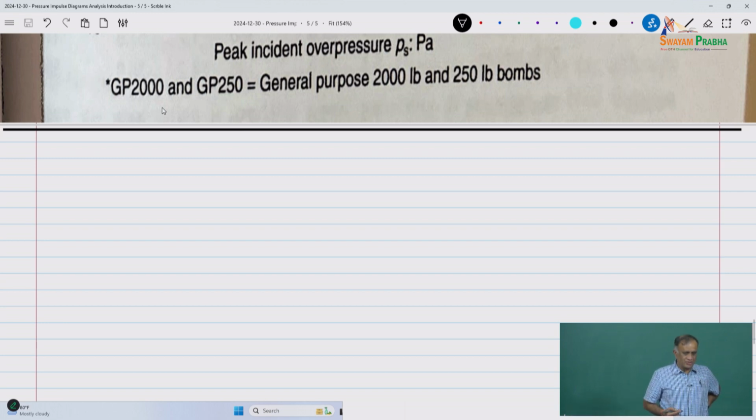So for example, the SDOF and whole Excel program of an SDOF response. You give a structure, maybe you can develop it for steel, concrete, masonry, precast, pre-stressed, anything that you want. So your inputs are going to be the structure properties, what are the sizes, usually if it's a wall, 1 meter width or 1 unit width is considered, and then develop all the section properties as we will discuss in the next couple of classes, and then develop the response of it.